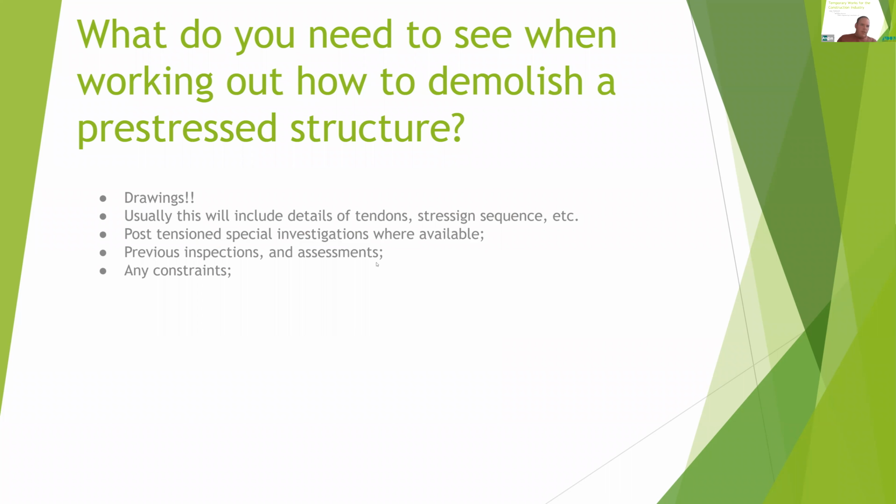So what do you need to see when working out how to demolish a pre-stressed structure? Ideally, you want the drawings. In an ideal world, you would have the drawings for the structure that would include everything to do with the post-tensioning or pre-stressing system that was used.